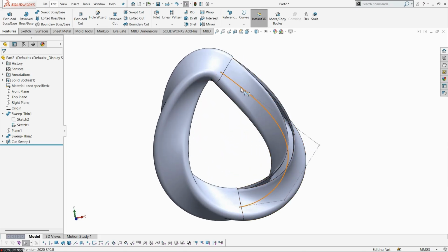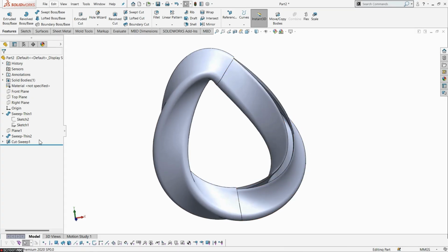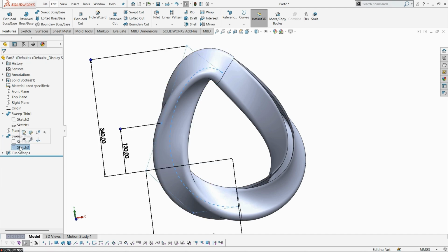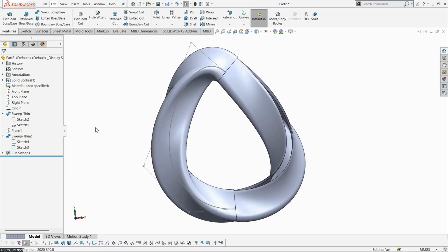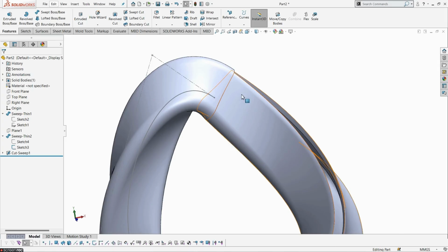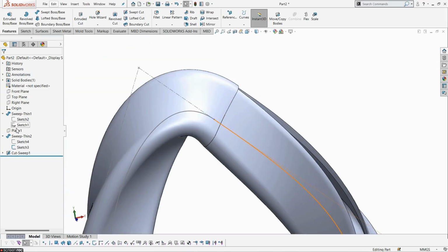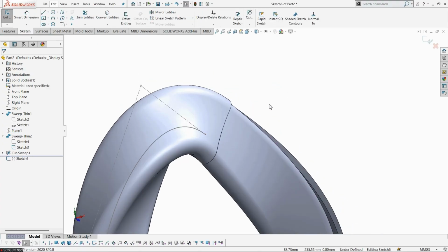Now, using the same kind of pattern, we are going to create a pocket at the opposite solid body. Okay. First, we need to turn on the entire 2D sketch. Go to this particular sketch, show it from the sections, then select a face, or we can straightly choose a plane to draw a new profile, because we already created a plane on this face itself. Using this plane, we can draw a pocket profile. Now just select this face and create a new sketch.